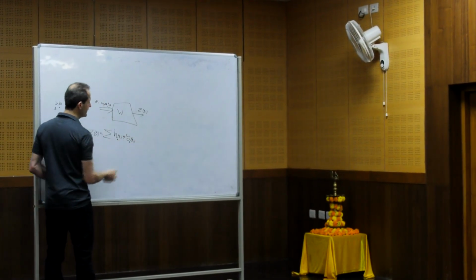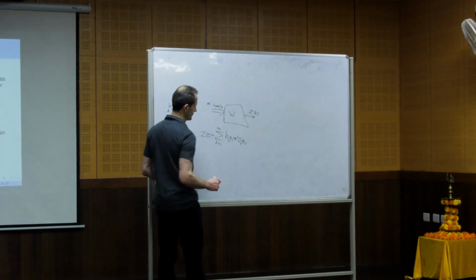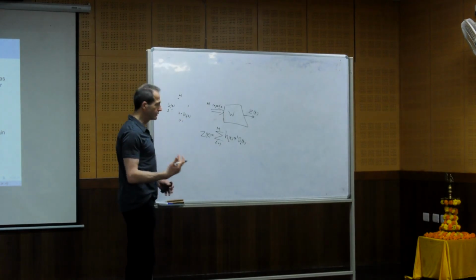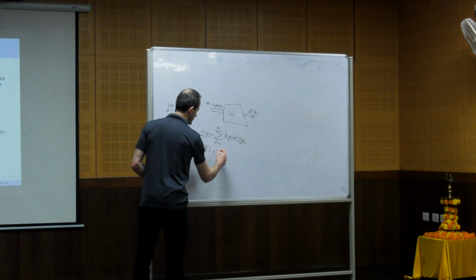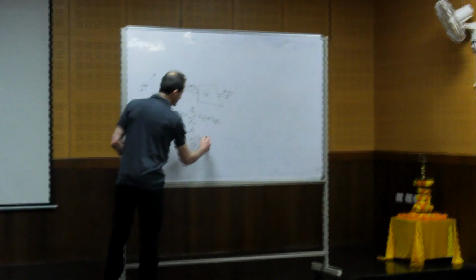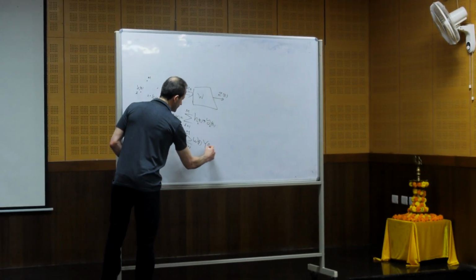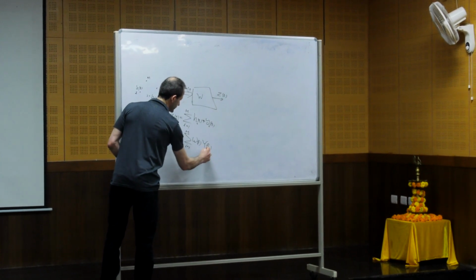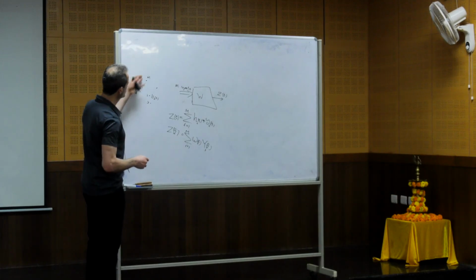These can be the weights, the filters, from i equals 1 to M. Or we can write it in the frequency domain as Z(f), the summation from i equals 1 to M, of some weight W(f) times Y_i(f). So this is like a superposition of the signals that we measure by the sensor array.